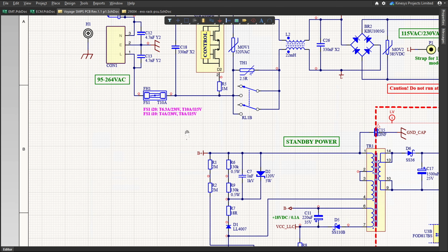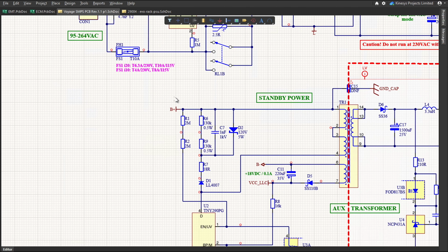Finally, if the voltage surge is severe enough and it doesn't go away, what we use is a so-called crowbar circuit. What a crowbar circuit does is short out the power supply in the event of a continuous surge or an overvoltage condition, and it will do that until the overvoltage condition is gone.